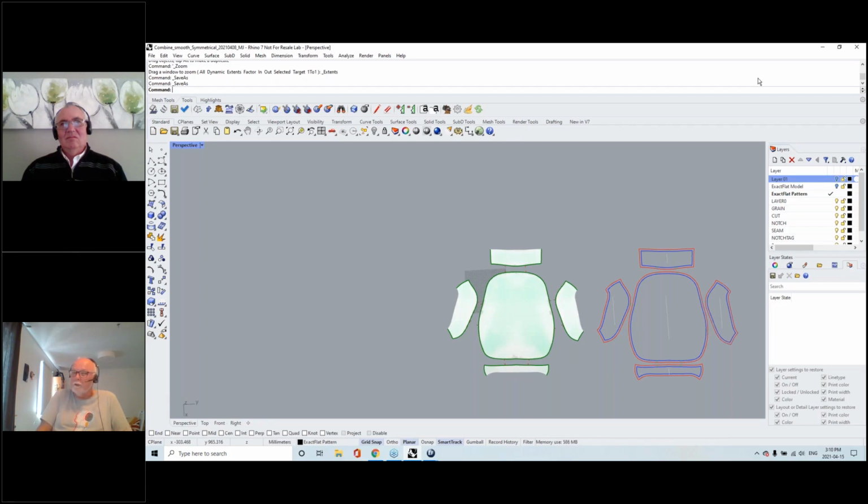Again, the person asking the question might be asking about the standoff from the object being scanned, and the standoff distance, as you saw, was about 10 to 15 inches with an indicator on the screen. But everything it sees within that patch of light that you saw flashing gets acquired. So as you move around, the volume that you can scan just expands.